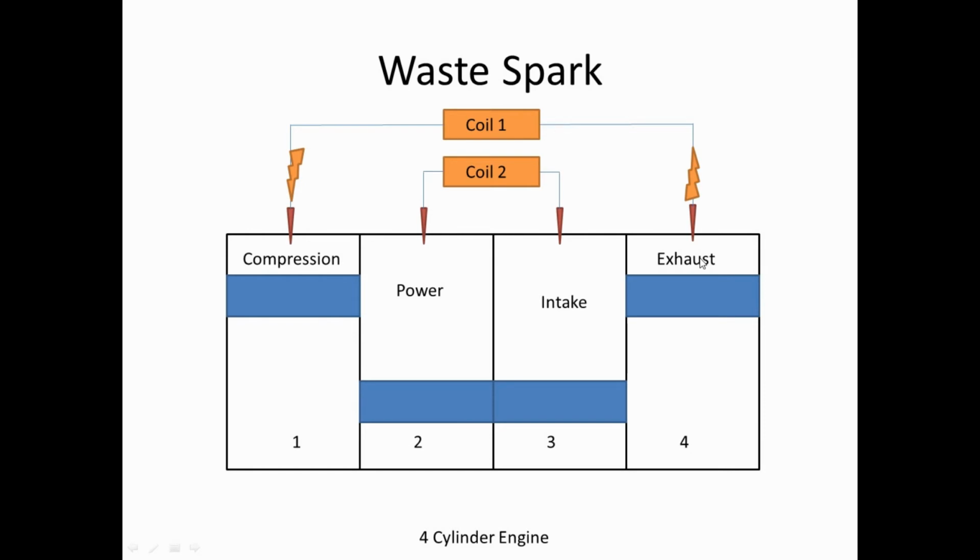So this actually provides a very odd wear pattern on cylinders 4 and 3 in this case. Just the nature of the beast, it's just the way it works. Because electricity has to flow in a circle, this is the direction it flows. So cylinder 1, the fuel gets ignited on the compression stroke, and because it's called a waste spark, cylinder 4, the spark is just wasted.